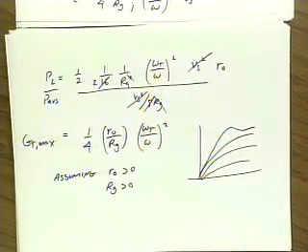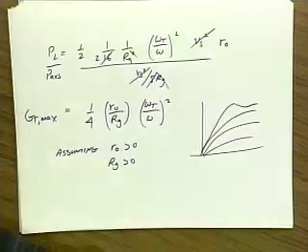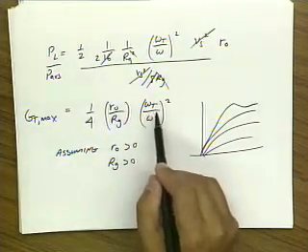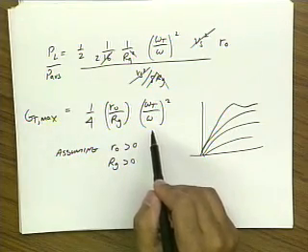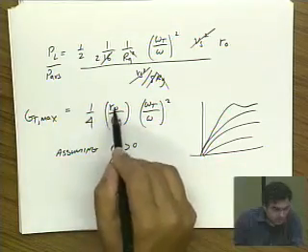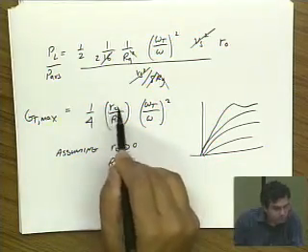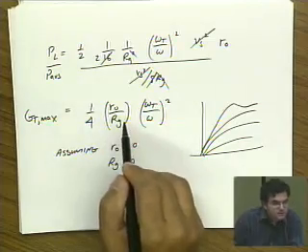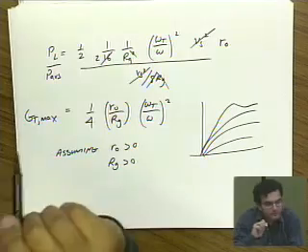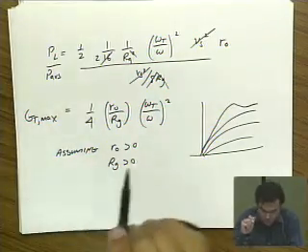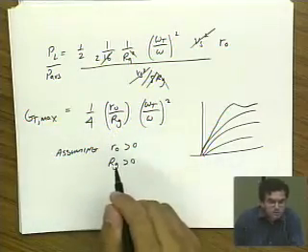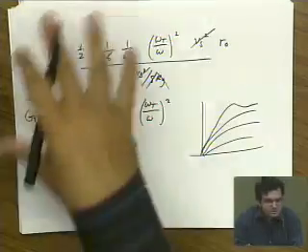Okay, this is actually a really nice result. It tells me that the maximum gain I can get out of my device is a ratio of the omega t of the device divided by the frequency of operation. And then it's also determined by the ratio of the output resistance to the gate resistance. And remember, at the very first lecture I said if you don't have gate resistance, you don't have a physical MOS model. And that's because if there were no gate resistance, power gain would be infinite, right? And we didn't need to do all this analysis.